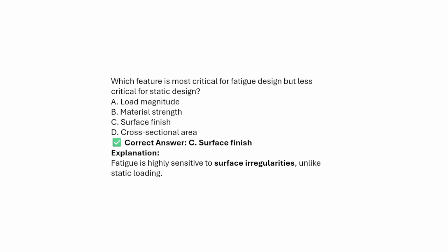Which weld feature is most critical for fatigue design but less critical for static design? Option A, load magnitude; option B, material strength; option C, surface finish; option D, cross section area. So the answer will be surface finish. Fatigue is highly sensitive to surface irregularities, unlike static loading.